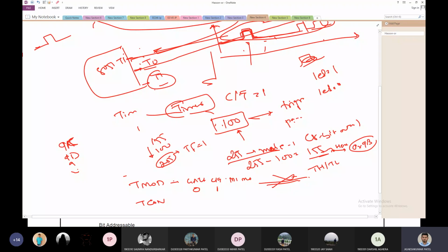Mode 1 and mode 0. What I'm going to do with mode 1 and mode 0? Obviously I have selected mode 1, that means I have to select mode 1. So this is the number and all other 4 are 0. Why? Because I'm not using timer 0. This is part of timer 1. So which number is this? This number is 0101, that is 8421 4 plus 1, 5. So 0x50 is the number. I have to write TMOD equal to 0x50.